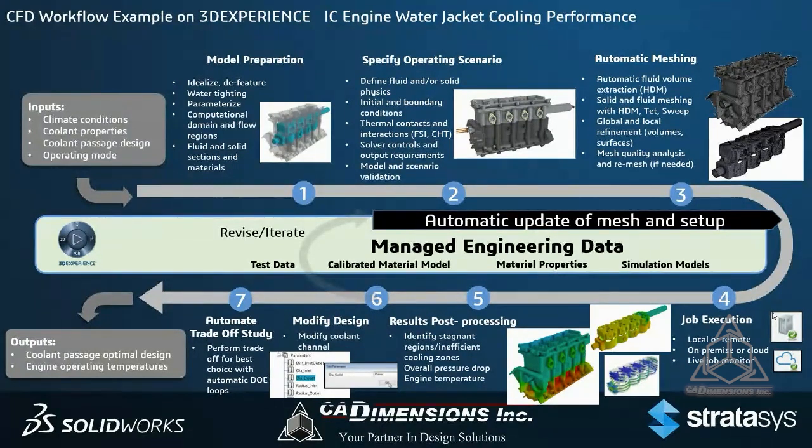The post-processing is exactly the same, right? Depending on what we're looking for, we can either take a look at pressure drop, make sure we're maintaining a specific temperature on our engine so things aren't overheating. If we're looking for inefficient cooling zones, we can go ahead and post-process exactly how we would normally on desktop. The results post-processing is exactly the same.